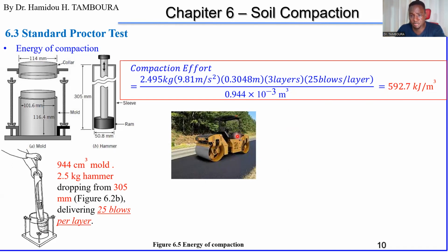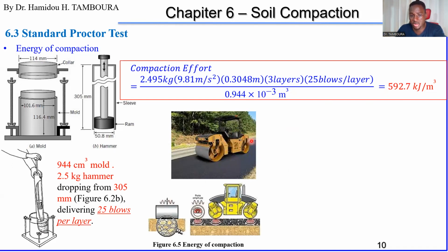When it is running, the space within the soil particles is reduced and it is compacting. The amplitude of the force depends on the speed and how many times this machine will pass on this soil. The asphalt will be well compacted or not depending on that.